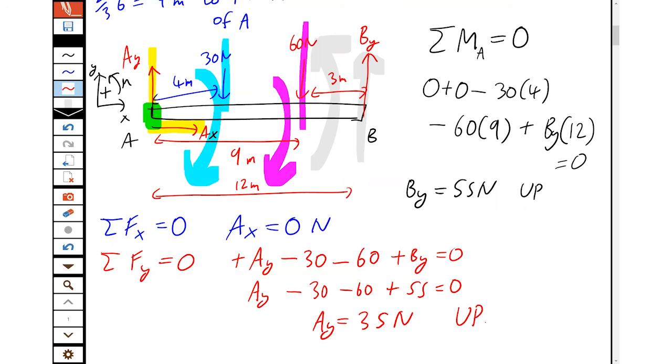And you can do that for any distributed load question. You reduce all the distributed loads to equivalent forces, and you can solve just like a force problem. Just remember, if later on in the problem you cut it apart or you break the distributed loads into pieces, like if you've chopped the beam halfway, then you have to do the equivalent forces step again. You just can't assume that everything's the same as before.